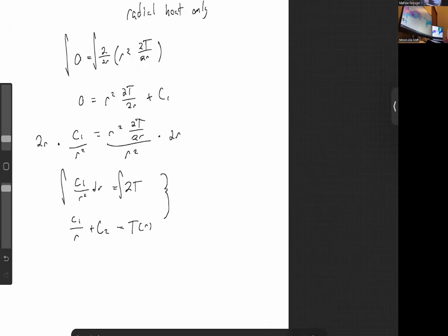So with this, we're going to apply Fourier's law. We're doing this for two reasons. One, we want to find the C1 value, and two, we want to put heat flow into this. We want to put Q in here because that's going to be our current in this case for the equation. So Q equals thermal conductivity, and then the area of a sphere would be 4 pi r squared, and then multiplied by dT over dr.